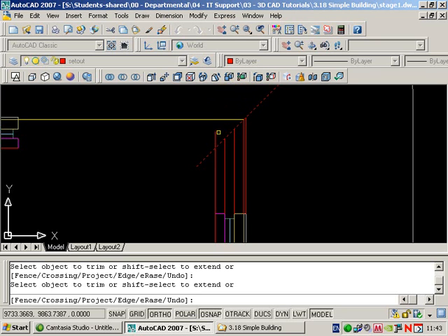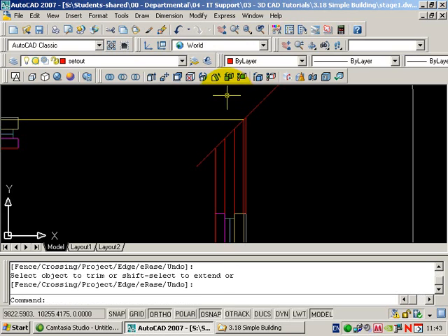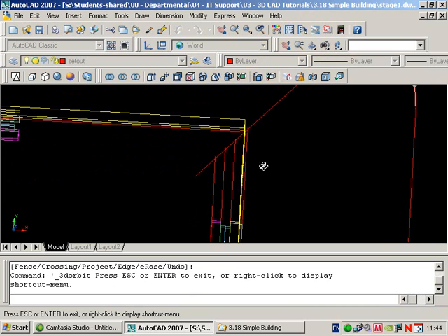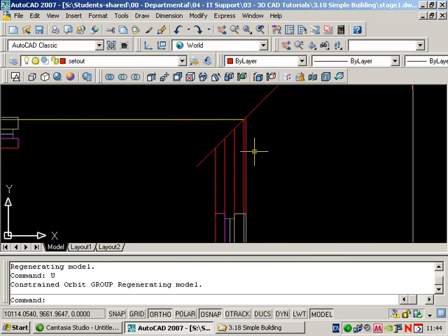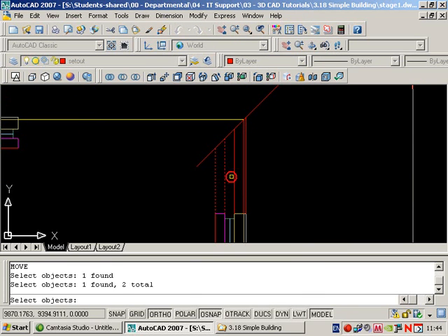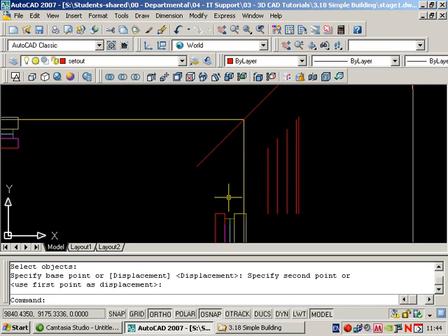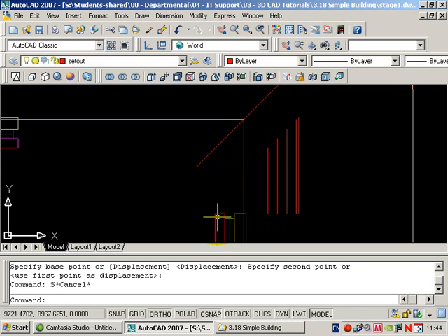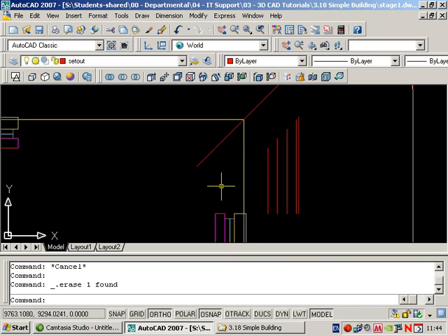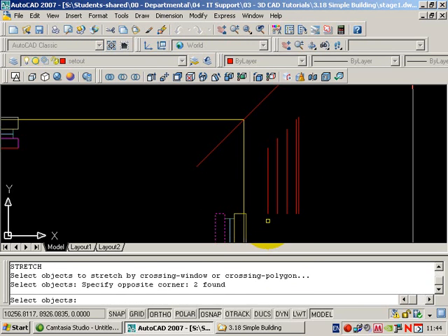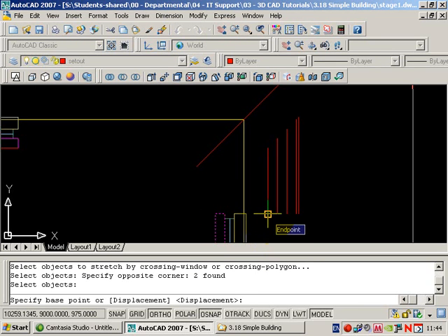These might not be touching each other in 3D space at all. If I rotate, you see there's daylight between them. But when viewed straight down, the command still functions properly. We then need to move these out the way to use as reference lines, just like we did when we stretched the window. So it's the stretch command again. I'm just going to delete that red line there. So S, return. Very carefully capture just one corner at a time and use its relevant reference line.